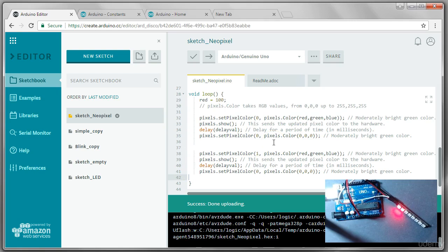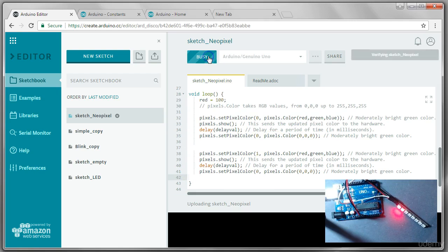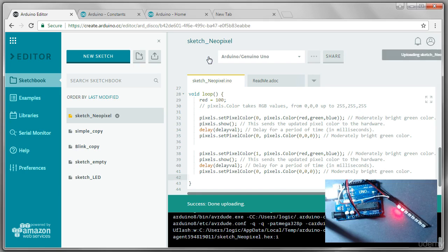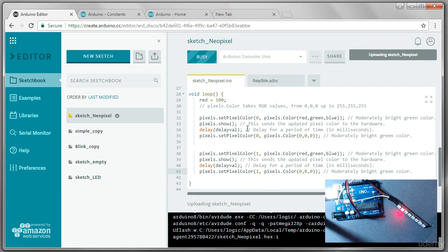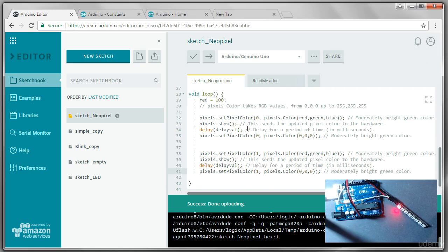So now it should basically do the first two LEDs back and forth. See if that works. Well, looks like it's kind of working. I think the mistake I made was I needed to erase the same LED that I had written to here. So let's try that. And now we can see that the LEDs are basically moving back and forth.